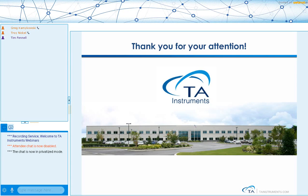And it helps if you know that going in. It's still a little difficult to go from a rheology program and getting molecular weight distribution to what you would get on a GPC. So they actually work pretty well together when you get data from both. But if someone has a material and they say, well, is this unimodal or is it bimodal? I don't know. Will the software tell them? Not necessarily. It's still a little bit difficult to do that.